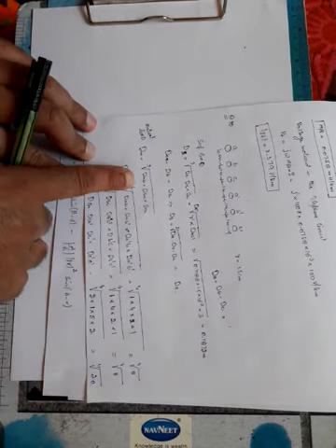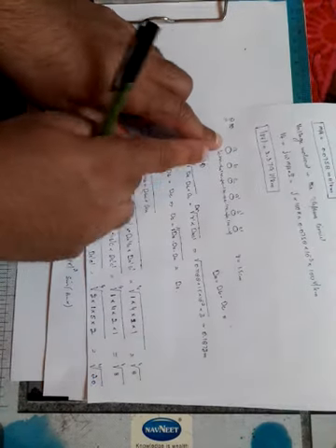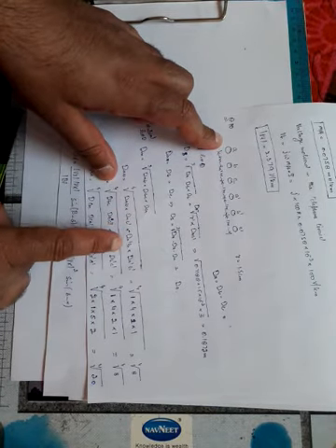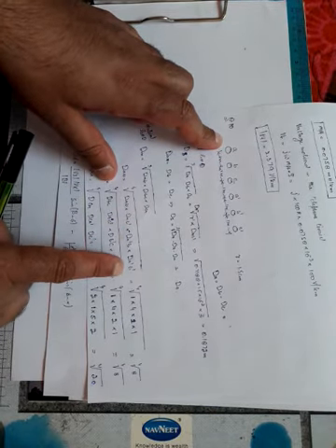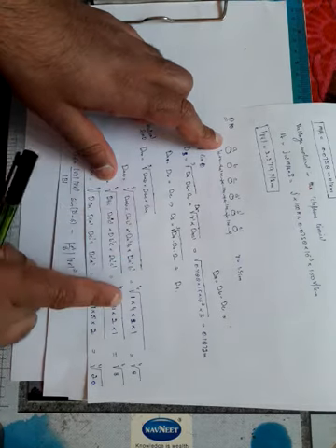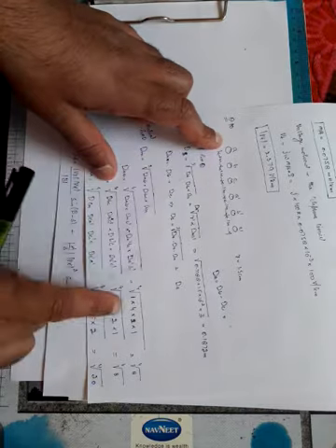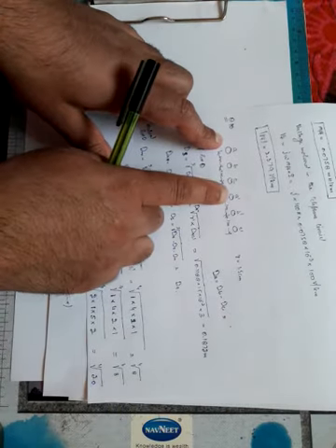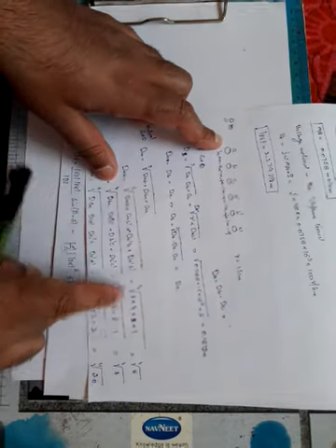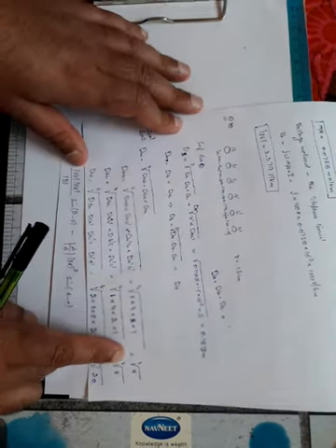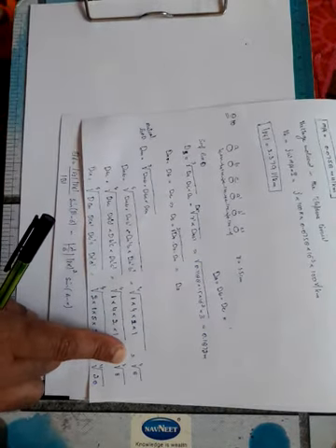So DAB is the distance between A and B, that is AB, DAB dash, DA dash B, DA dash B dash. So DAB is equal to 1 meter, DAB dash, 1, 2, 3, 4, 4 meter, DA dash B, A dash B is 2 meter, and DA dash B dash, that's again 1 meter. So it will be equal to the 4th root of 8.